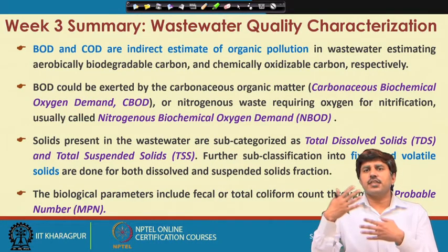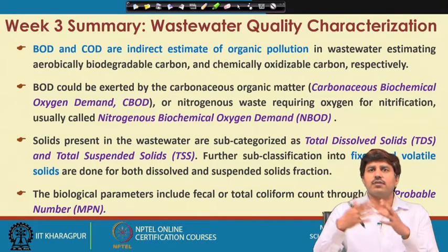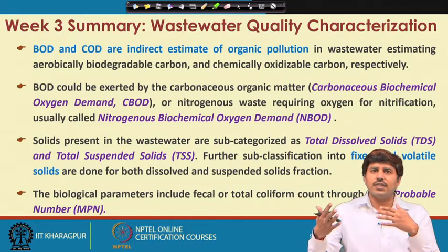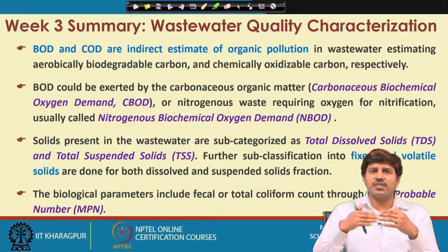Then if we expose it further to a furnace at 550 degrees Celsius for 20 to 30 minutes, the solids that escape the system we call volatile solids, whereas the solids that still remain we call fixed solids.